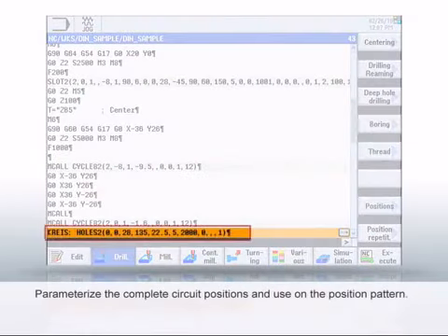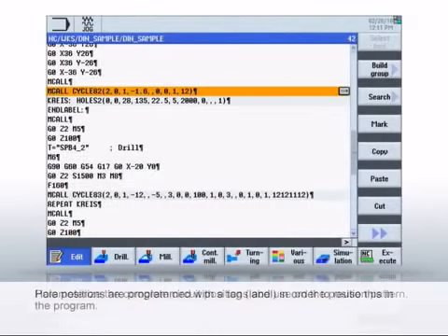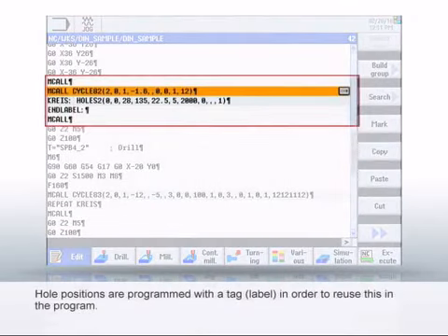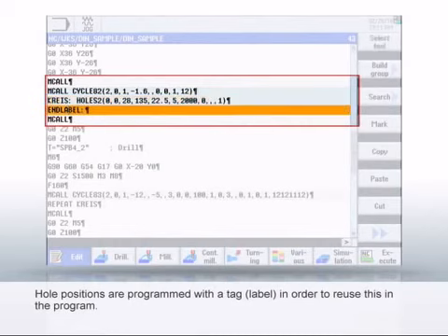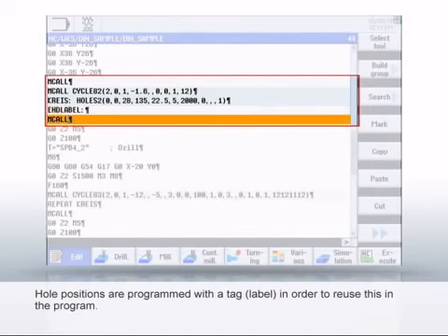Now create an arc with 5 holes. The drilling cycle is now used for the drilling positions. You'll have set the tag circle because a thread should also be tapped on the drilled holes of the position pattern.